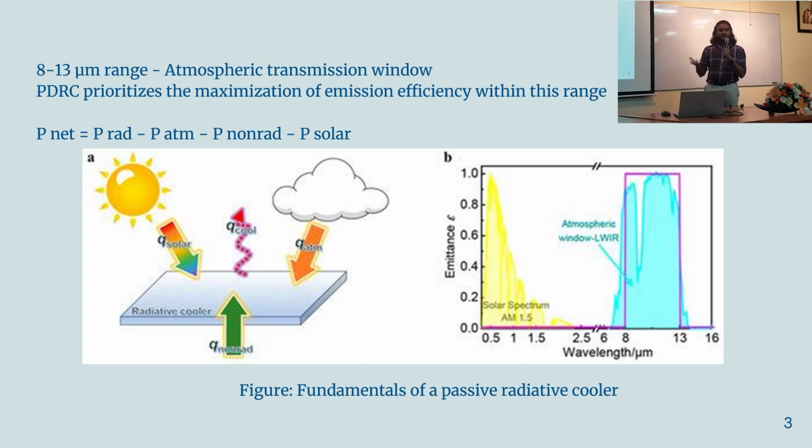That material would have thermal energy. The coating would absorb that energy and emit it as electromagnetic radiation. So in this study, I focused mainly on the solar radiation and also the radiation that the object itself emits. The other two are negligible compared to the ones that I mentioned.